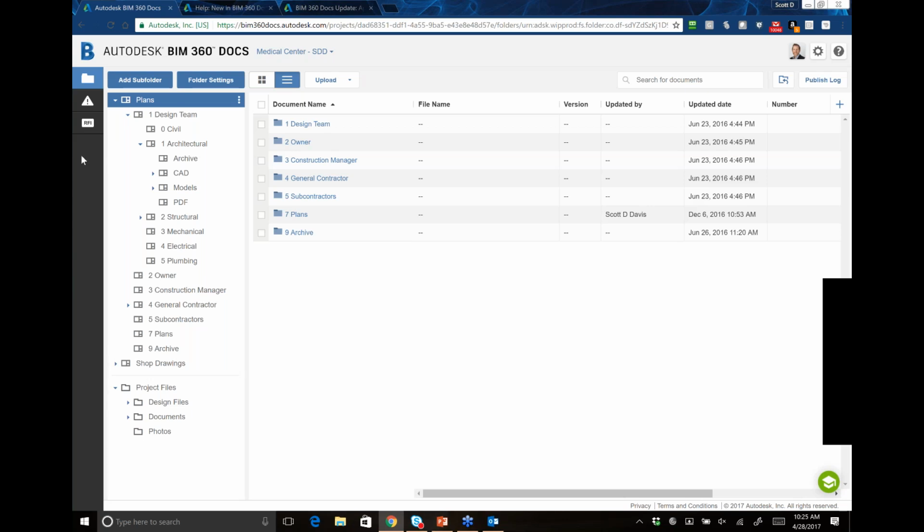So earlier when I talked about, in the PowerPoint slide, a single source of information, this is really it. You're going to be able to log into your BIM 360 site, and you're going to have an entire series of tools, functionalities, and workflows that are all available for you from a single source of truth, a single set of information, this common data environment, rather than what you might be doing today, which is putting an RVT on a Dropbox site, and then maybe another consultant wants it emailed to them, and another one wants it on an SCP site, and then another member of the team wants something uploaded to something like Newforma, and now you've got that same exact data in 4 different locations.